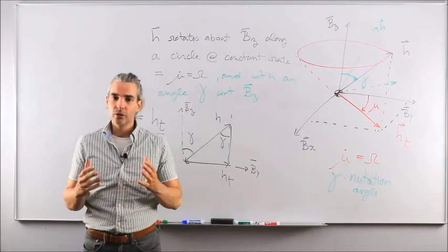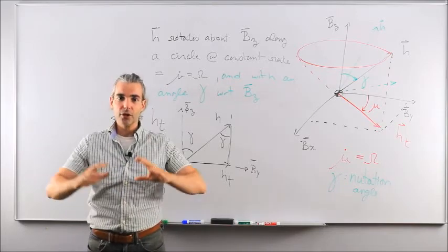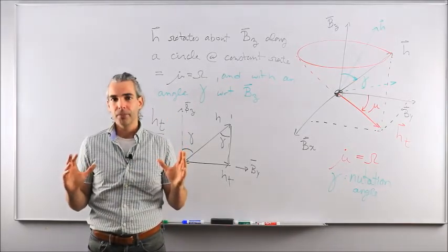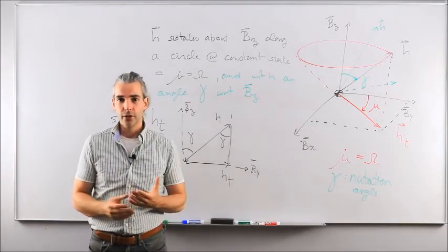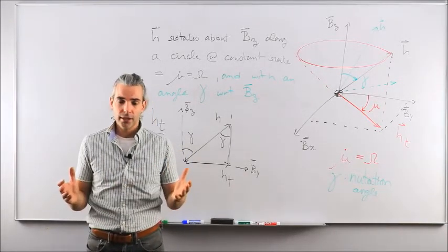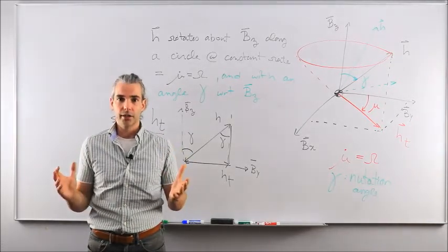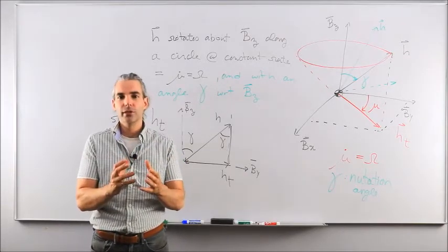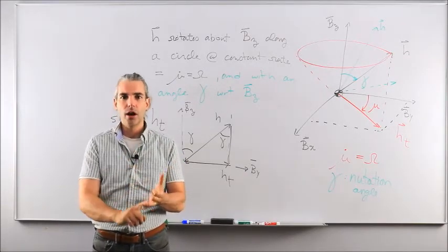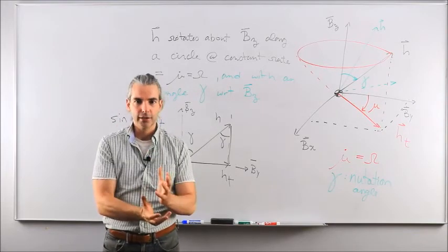Keeping in mind that the initial values here are crucial for the entire analysis, because if there's no torque applied to the body, and at t equals 0 the components of the angular velocity vector are all equal to 0, that would just mean that the spacecraft would remain stationary. But if the spacecraft had some initial velocity components, omega x naught, omega y naught, omega z naught, the spacecraft would keep spinning in some ways.